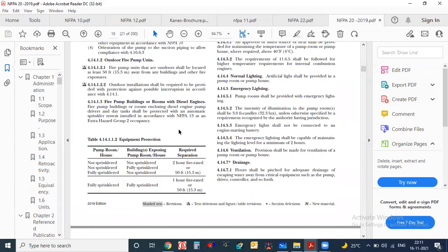Fire damper is done by HVAC people actually. I know, but for what reason is it in firefighting? They can mention it anywhere because it is related to fire. So you will find in NBC also that they talk about fire dampers, because a fire damper is a very common piece of equipment which can be used by HVAC or firefighting.